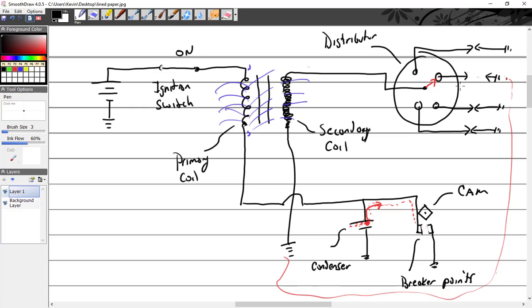If it's got a very small gap, it's going to build up just a little bit because current can jump across that and flow. But if you have a very large gap, it's going to build up to its maximum, if it can, to jump that gap. So the further apart you go, the more voltage it is. And that's why in our magneto tester, the gaps on those little pins have to be calibrated.